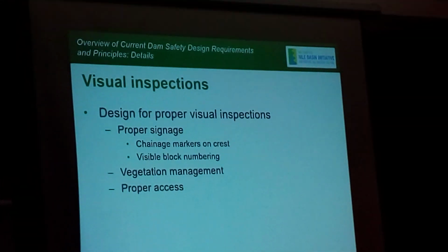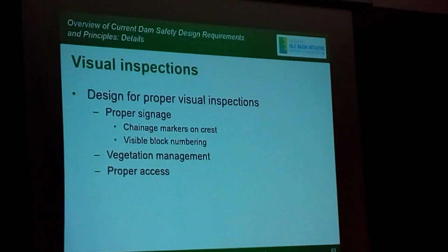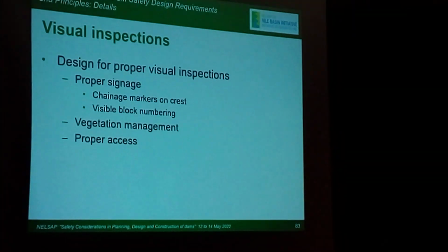All right. Then the other thing, you have to design for vegetation management. I've seen it many times. People build a dam and then they keep the tree right alongside the embankment or the dam wall. We have the thing that at least the height of the dam, there must be no big trees, and you must do vegetation management away from the toe of the dam.